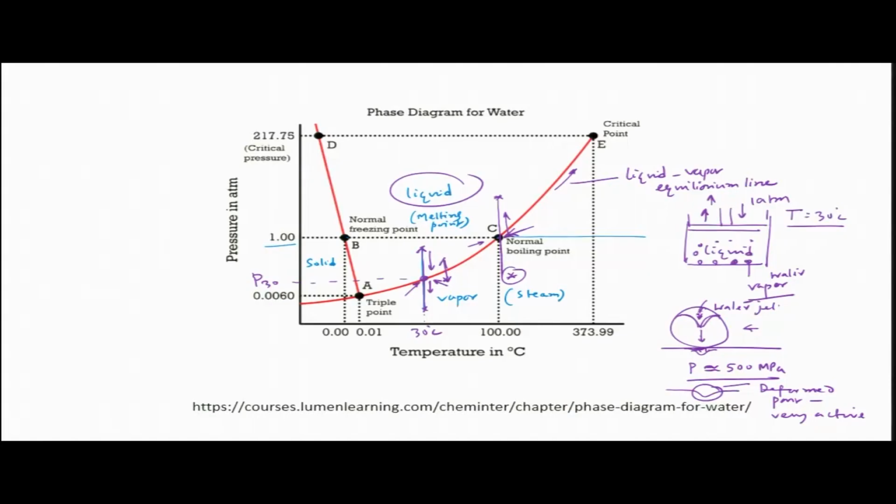So, now in the beginning of that vapor formation process, we need a low pressure, and then if we increase the pressure, those vapor bubbles will collapse, and that collapse happens in this fashion, that it constricts and then breaks open, and when it breaks open, this water jet will come sharply over the metal surface and it will deform, and after deformation that deformed part will become a very active site for corrosion. So, that particular site will corrode at a high degree. Okay. So, there corrosion happens.